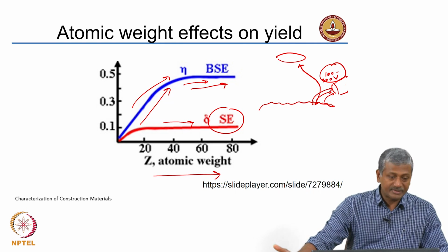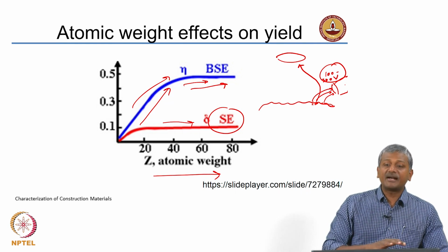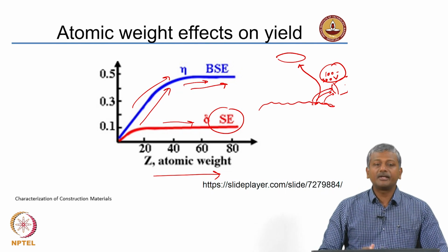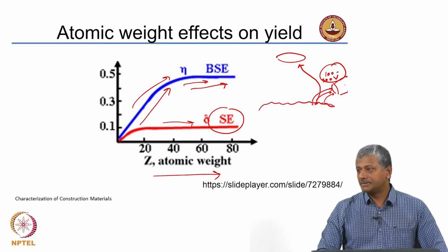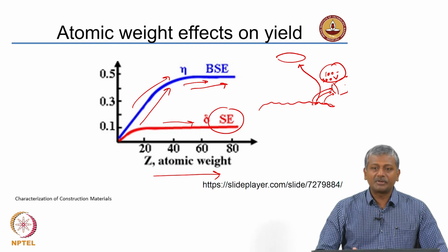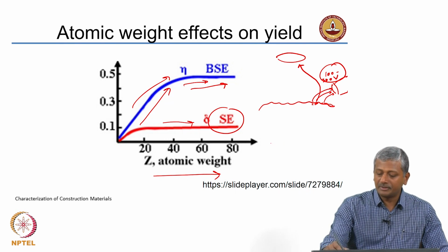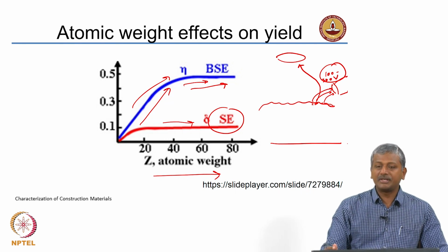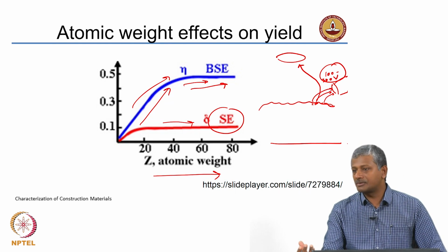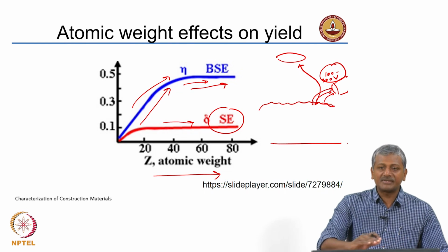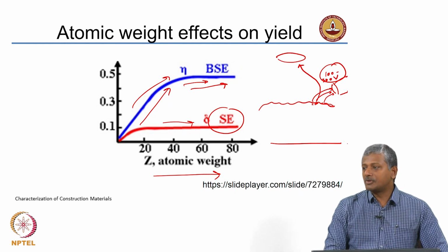So, for example, if you have a very flat specimen and you are trying to look at it with a secondary electron detector, okay, you will not really see much of an effect, because in a flat specimen you have almost an equal number of electrons from the surface that will go towards the secondary electron detector. So, there will be no difference in the surface morphology, right.